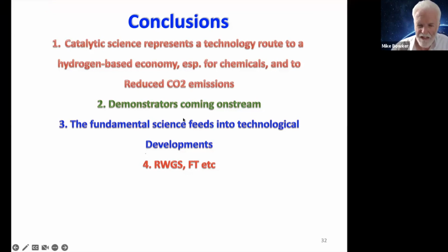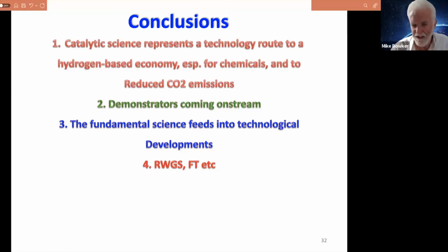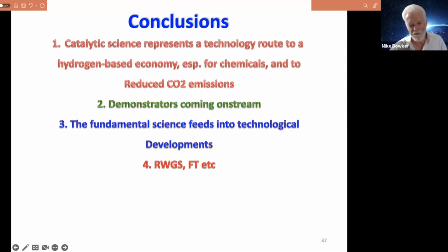So that being the case, we need better reverse water gas shift catalysts in front of the methanol synthesis plant that produce in the end a mix of CO2 and hydrogen, and probably do that global conversion I talked of earlier. That is a CO2 hydrogen mix, which actually works by globally CO hydrogenation and is a dry process. But also we need new Fischer-Tropsch processes, a lot of work going on in that direction with CO2 and hydrogen, maybe more on methanation and a whole range of other kinds of reactions.